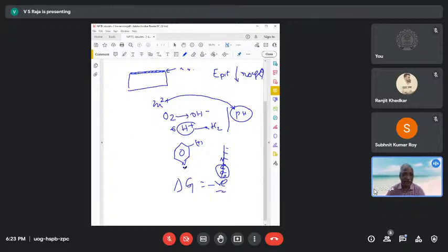For example, some inhibitors we say have about 90% efficiency. They can reduce corrosion by 90%. Some of them only 45%. What has happened? The molecule has a different ability to get absorbed on surfaces. For example, let's say I'm going to use benzotriazole, BTA, or triazole. They use it for copper alloys. These inhibitors form a very nice, thick film on the copper surface. This is called film forming inhibitors.